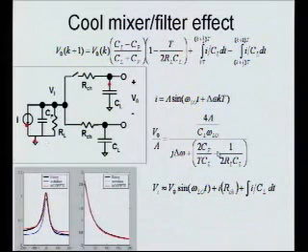That's the answer. And the rejection you achieve, you said it's 10 dB? So this bandwidth here, the rejection down here comes from this term here, proportional primarily to the channel resistance of your on switches. So basically, if you had none of these terms, then the V out just drops with frequency. But at some point, you hit a floor set by this kind of RF term. So in this case, it was about 10 dB. And I've tried this in other processes, and that always seems to be a limit. It's really hard to get better than 10 or 12 dB.